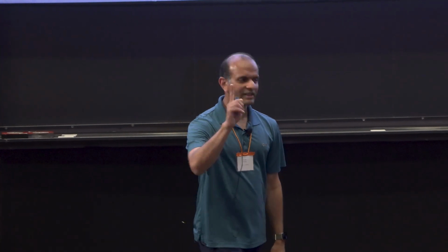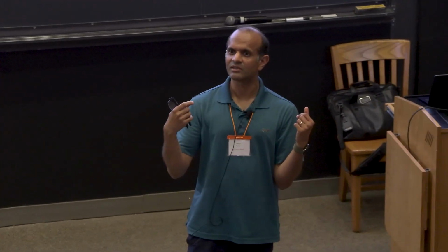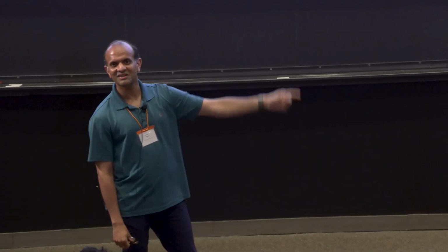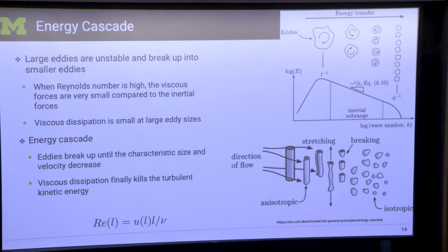That's too simple, a histogram. So what people do in turbulence, they make it complicated. So you take that length scale, you take 1 over that length scale for no apparent reason, and you multiply by 2 pi, and you get frequency, okay? And that's the x-axis, wave number, in the top plot. So you take that histogram, you do some mathematical manipulation, you get that plot on the top.